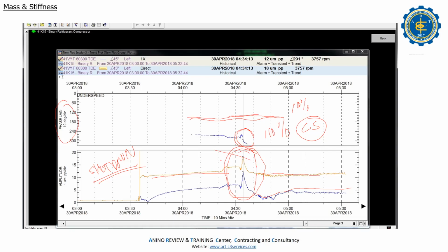Okay, give me the data. That's the important thing. Give me the data. Critical speed: there is a change in the phase angle. No change, then it is not. How do you know that is the critical speed? If you have data like this with the phase angle: high vibration at 2,500 RPM, then a phase angle difference of 180 degrees, so it is a critical speed.